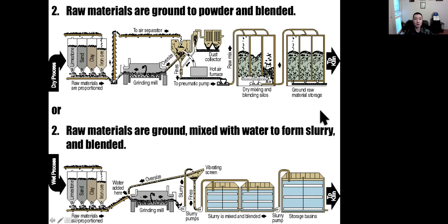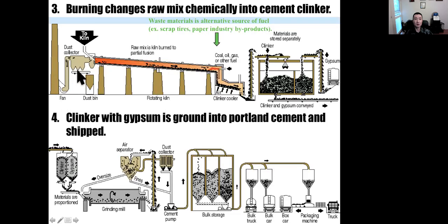The next step is we put the raw materials into the kiln, which is a big oven with a certain slope. The size of the kiln is very big. It slowly rotates, so the raw materials will go from the higher end slowly to the lower end. At different locations, different chemicals such as C3S, C2S, C3A, and C4AF, which are the major compounds in cement, will be produced. At the lower end of the kiln, we have clinker.